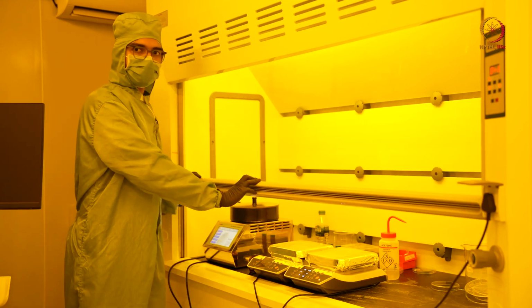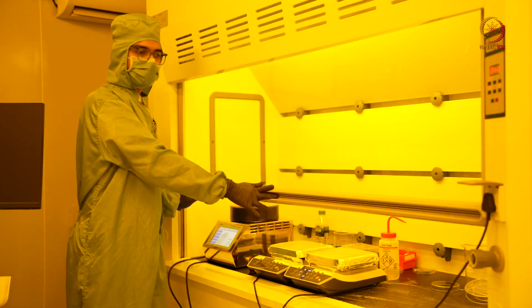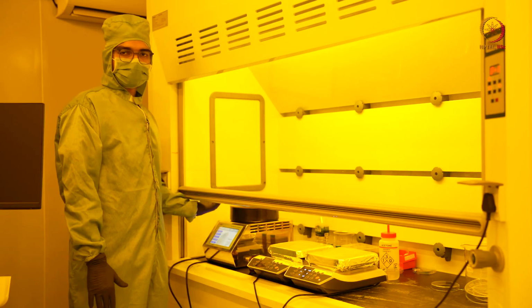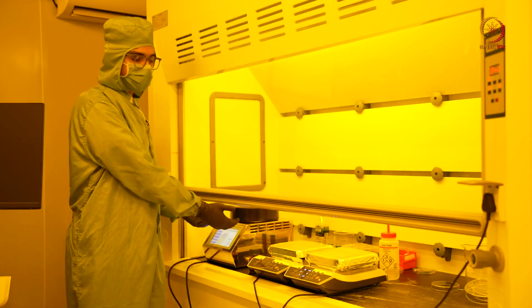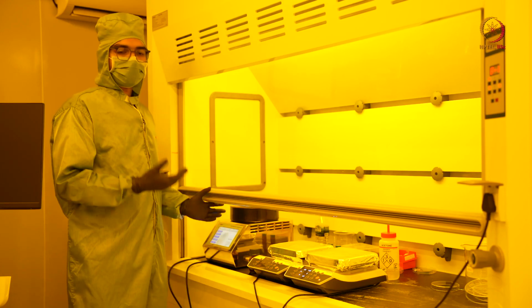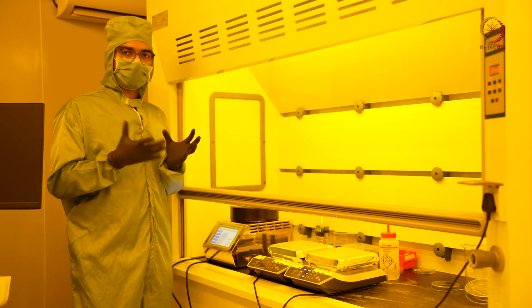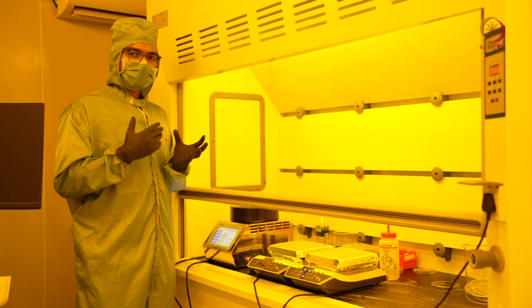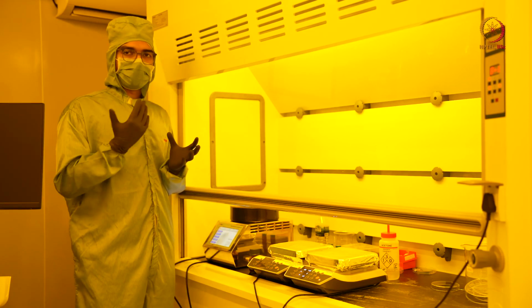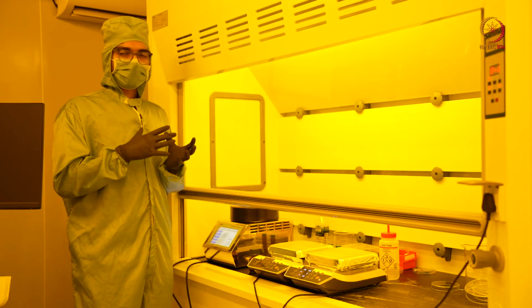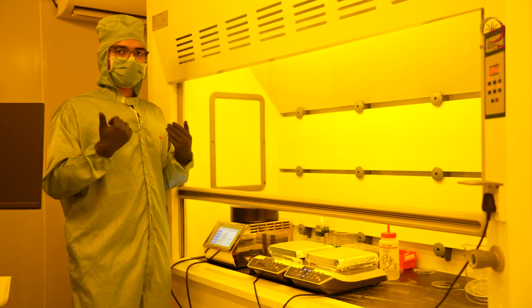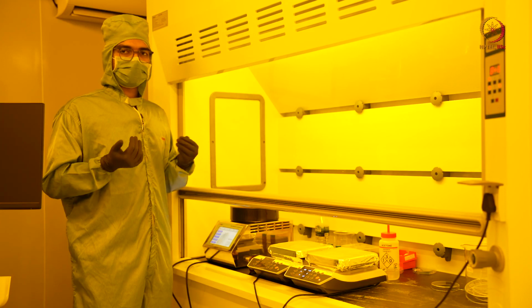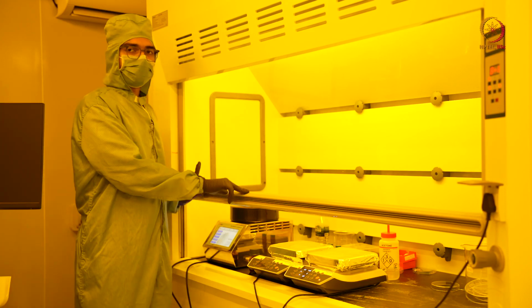Okay, if we close the fume hood lid like this, the laminar flow that is installed within the fume hood will prevent any volatile gases from coming outside. The photoresist, as I said, is a fluid-like material, right? So the solvent will evaporate so that it gets hard, or the photoresist gets hard by the evaporation of solvent. So to prevent ourselves from breathing in the solvent, we use a fume hood all the time.